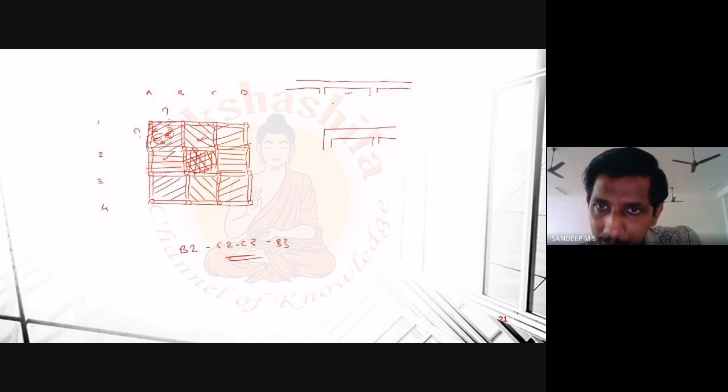Okay, I hope the concept is clear to you. The main thing that you have to notice is that when you have a continuous beam or continuous slab like this, you will have a positive moment here at the mid span, and you will face a negative moment at this location, that is at the support location. So you will be having negative and positive moment. In the normal case the negative moment will be on the support, and the positive moment will be at the mid span. I hope you are able to get the concept. So when you have continuity, you will have two types of moment. One is negative and another one is positive.